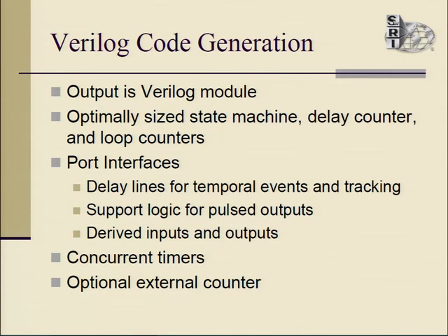Now, if you take that timing program and generate it as Verilog, and to be clear, you can take almost any timing language program and go to C or go to Verilog just by different options when you call the compiler. But when you do go to Verilog, you get a Verilog module. Inside that module, you have an optimally sized state machine, optimally sized delay counters, loop counters, using as few resources as we can. Here, the port interface as input and output ports, concepts are a little bit more natural to Verilog than the C call.